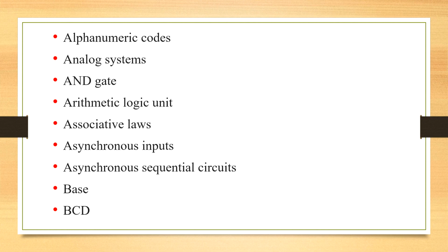The next one, asynchronous inputs. Flip-flops available in IC packages sometimes provide special inputs for setting or clearing the flip-flop. These inputs are called asynchronous or direct inputs. Next one, asynchronous sequential circuits. In an asynchronous sequential circuit, a change in input signals can affect the memory element at any instant of time.